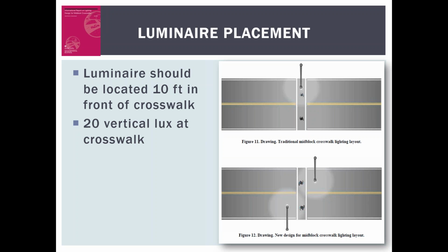That not only looked at lighting, but signs that are no longer reflective. Other issues may occur at night that you wouldn't see during the daytime. Signs that are not reflective look perfectly fine during the daytime, but they may have no visibility at night. Lights that are not working, internally illuminated street name signs on our traffic signal poles that are not working. And those need to be reported.